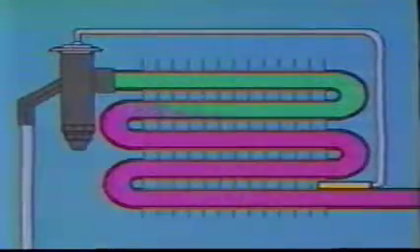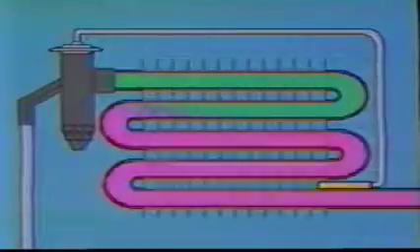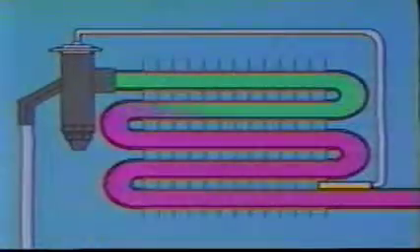Another method, the 2-temperature method, attempts to directly measure the saturation temperature. The saturation temperature can be measured directly if the liquid-vapor interface is located and is stable. Also, there must be minimum pressure drop between the locations where the 2 temperature readings are taken. The higher the pressure drop, the greater the error in using this method. The important point is that no matter the method used, an accurate determination of saturation temperature and outlet temperature must be made.